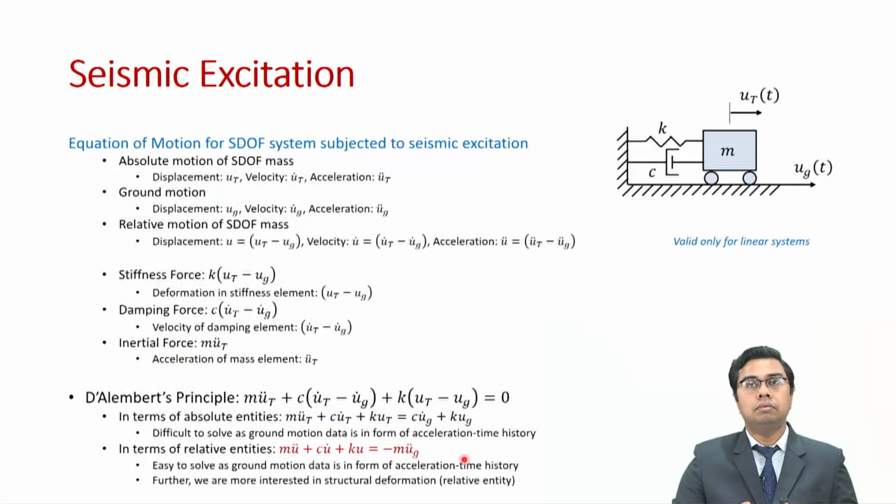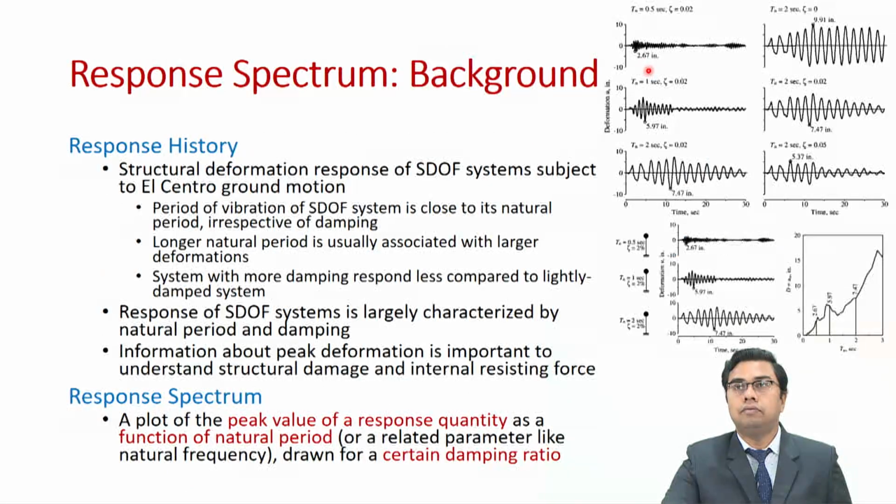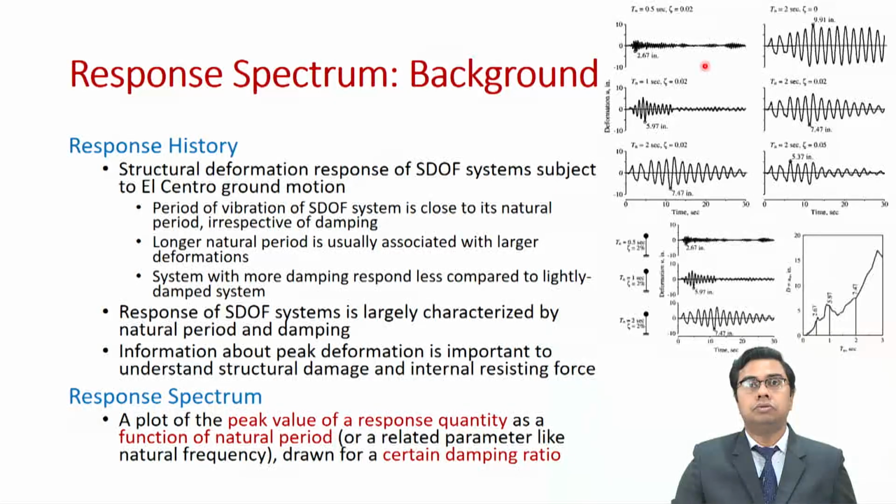Once we have obtained the equation of motion for seismic excitation, now let us look into some of the responses of structural systems during earthquakes. In this slide we have 6 single degree of freedom systems whose response has been evaluated when they are subjected to El Centro ground motion. We have earlier seen El Centro ground motion is one of the most widely used ground motions in understanding seismic response or performing seismic design of building structures.